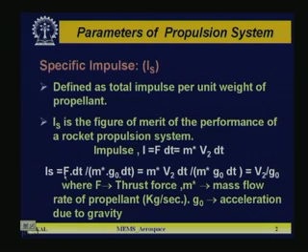So now if you simplify it, then F dt is given by m star V2 dt, then it comes to V2 by g naught. So that is the specific impulse IS, coming as V2 by g naught, where g naught is acceleration due to gravity and V2 is the velocity in that direction.